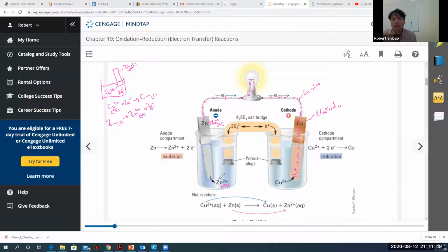And so in this way, even though the oxidizer is way over here, the oxidizer is going to be able to reduce something way over here via remote control, except the remote control is not wireless. The remote control is via wire. So there's a piece of wire, and those electrons are going to be connected all the way down through here. And so once it hits the zinc, we have the sea of electrons. So eventually we're going to find the weakest link. Now the weakest links are usually on the corners or the edges. So you can see, do you see the corners here and the edges are being quite corroded?